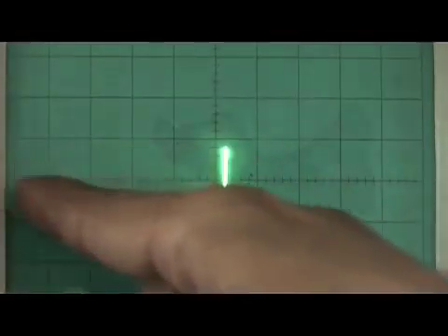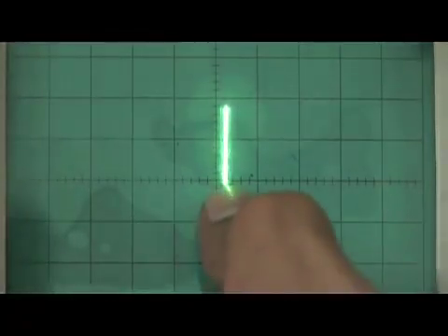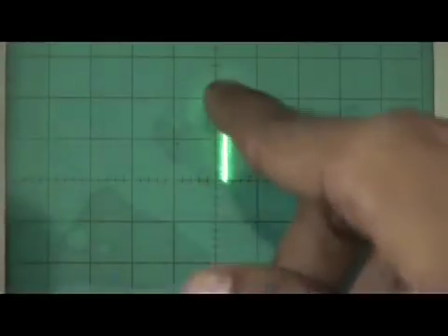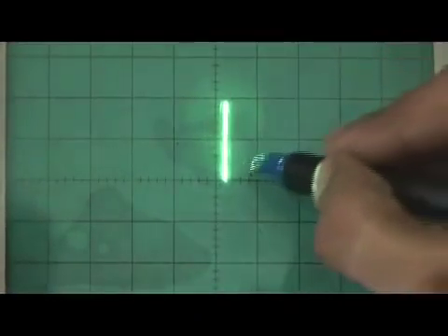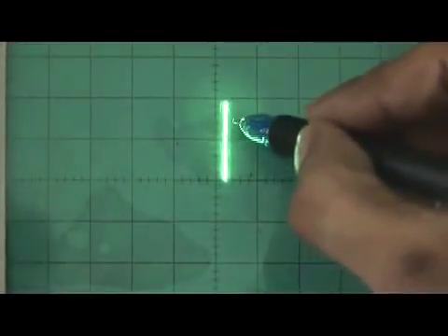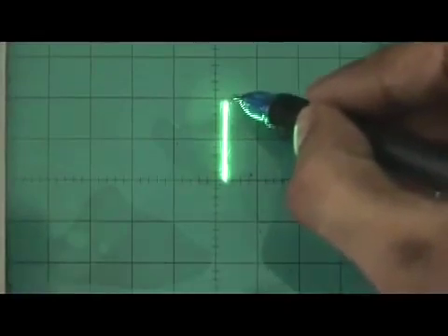Now, this dark black line, which has subdivisions, is your reference line. Using this y position knob you can move this line and bring it over here so that you can properly count the number of divisions. Now from here, if I count, it is complete till here, 1. From here it is 1.2, 1.4, 1.6, 1.8. It's almost touching 2 but not 2, so let us take it as 1.9. I release the XY.